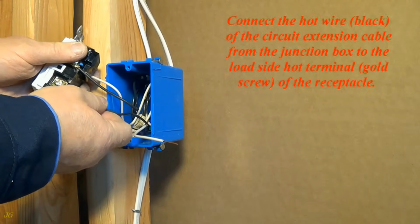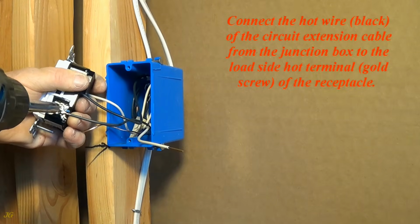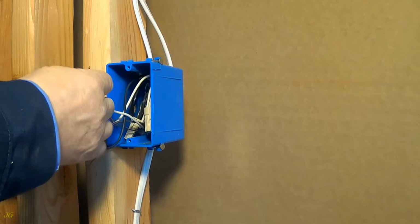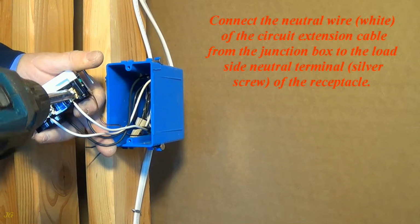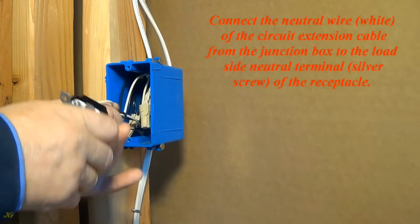Connect the hot wire, black, of the circuit extension cable from the junction box to the load side hot terminal, gold screw, of the receptacle. Connect the neutral wire, white, of the circuit extension cable from the junction box to the load side neutral terminal, silver screw, of the receptacle.